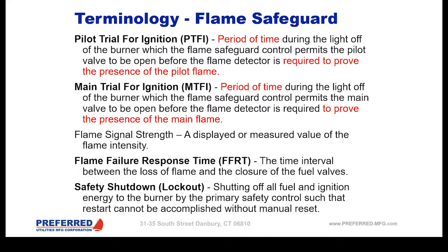And that's a very good point. I think the burn-in is also very important too, because if you're powered up for 4 hours straight, and I mean powered up, it will then burn in what those settings are. So it's very crucial that if you want some more time, you power down, then power back up. You definitely want your combustion technicians setting those dip switches and not somebody at the plant.